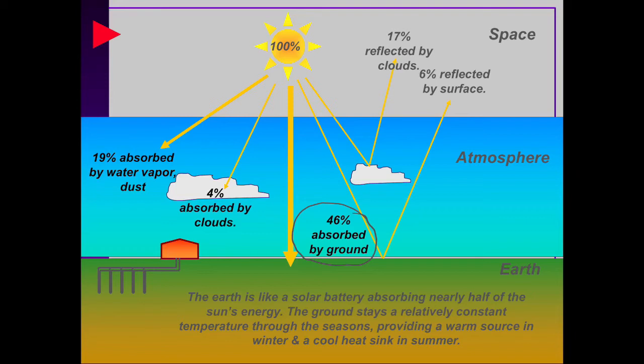Now, the ground temperature stays very, very stable, which is one of the other advantages of geothermal over an air source system. Whereas with an air source system you'll see the temperature of the air change significantly with the ambient on the outside, where the heat pump has to absorb heat, when you have a geothermal it is very stable. In fact, you'll see very little changes in the ground temps if they're properly designed. So very helpful, very, very good. It's one of the ways on these systems that you can really provide an efficient operating unit. It's by far the most efficient of all of the systems.